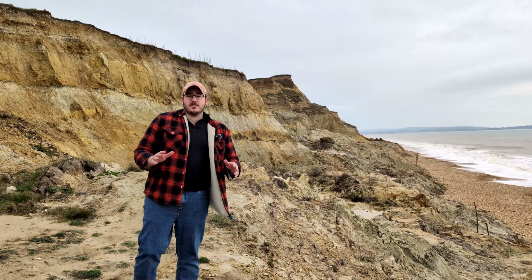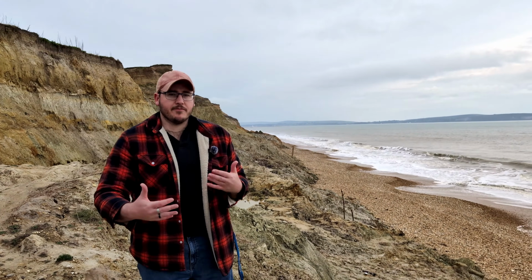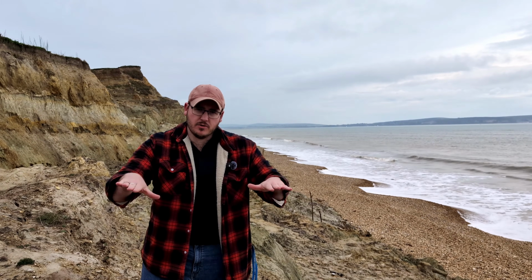So a couple of people mentioned in my last video to give a little bit more of a detailed explanation of how you capture photogrammetry data. In essence, it comes down to capturing as many photos as possible with as many angles as possible. Unlike doing an orthomosaic mission, where you're interested in mainly a 2D flat plane image, generating a map tile or something like that, our goal is to produce a model at the end of it. So you want to be able to capture as many angles as you possibly can, because that's the single most